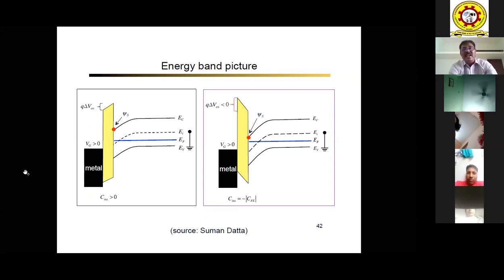Like I said, in quantum mechanical effects, one is the DOS, density of states, which is not uniform. That's one of the quantum mechanical effects. And quantum reflections. Then another one is the conduction band is not uniform throughout the channel. The conduction band edge is tilted at the surface. There are 2 types of things available. Okay, this is one-dot model, they call it, and we have approximate mathematical models for that, to what extent it's tilted at the interface. So that is why you see that it's tilted there, bend.